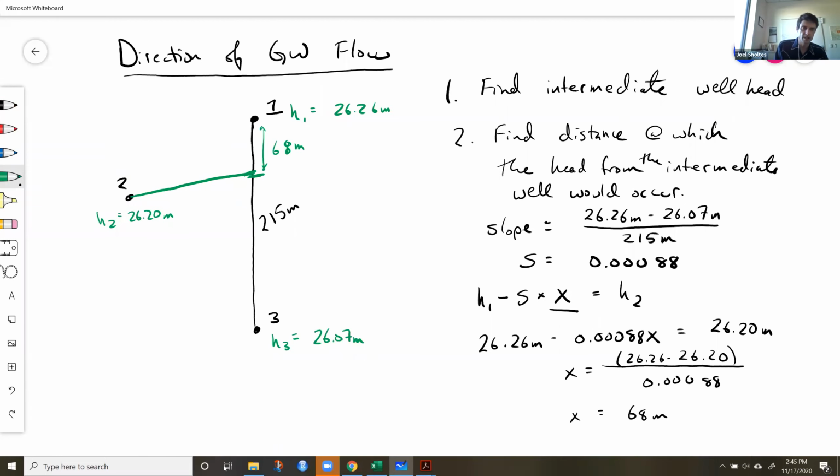And what we've drawn here then is a contour line, right? Where we have equal groundwater elevation from here to here, assuming that the groundwater surface is a plane. So if I were to dig a well at this point and this point and this point, I should, more or less, get this elevation of my groundwater in the well. All right, so we did some linear interpolation.